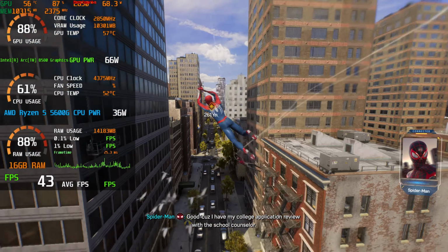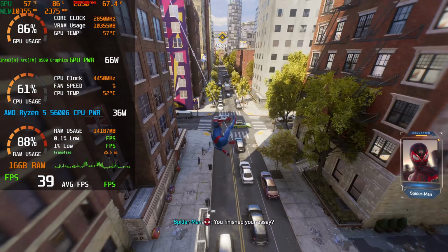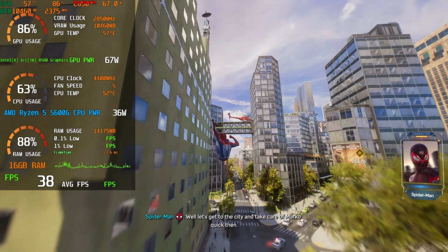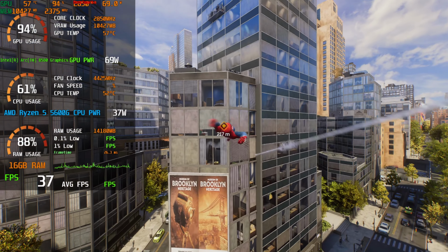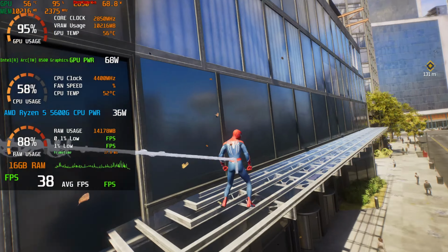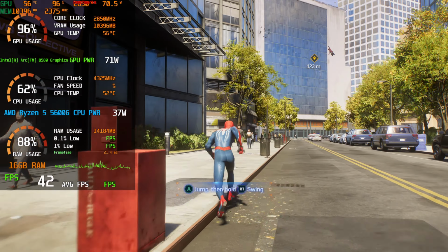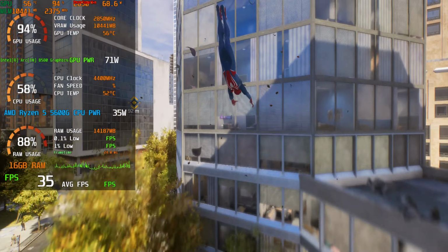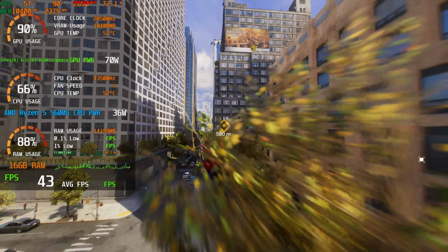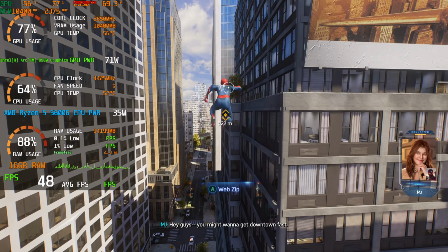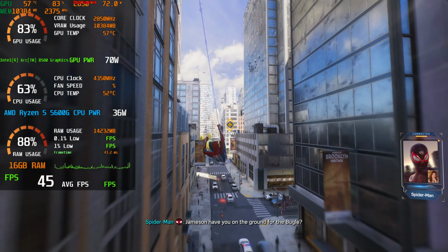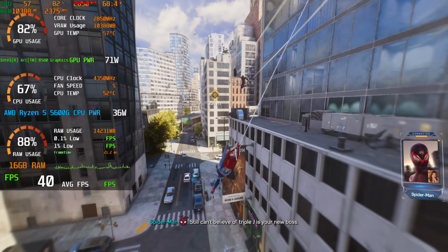Okay, so with these results in mind, it is safe to conclude that the Intel Arc B580 does indeed have a CPU overhead issue. My overall recommendation when it comes to using the Intel Arc B580 is to stick with DDR5 configurations. As you did see with the 8700G and the 8400F, there was no loss in FPS. And if you have to use the Intel Arc with DDR4 systems, then my recommendation is to use the newer X3D processors and probably 8-core 16-thread CPUs from this particular generation of CPUs.